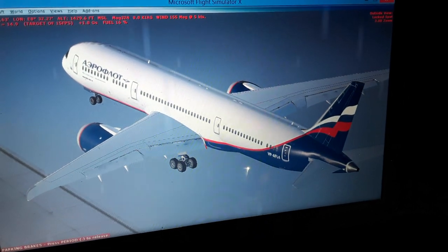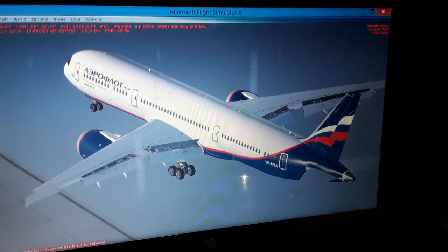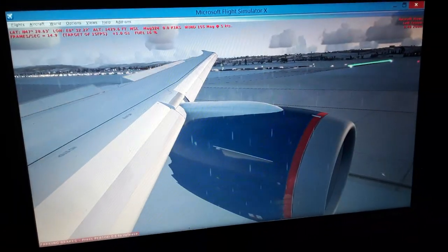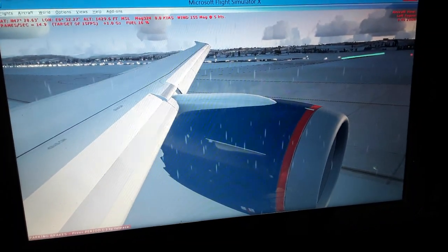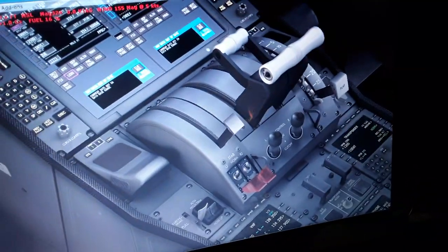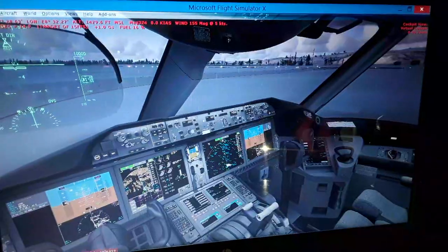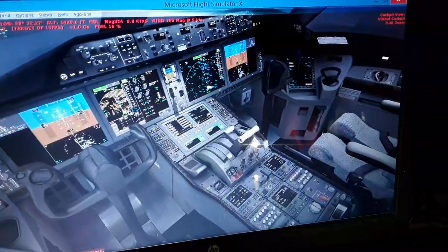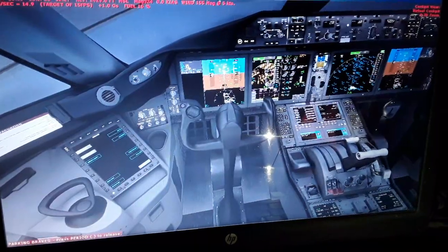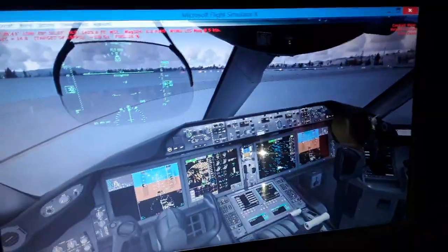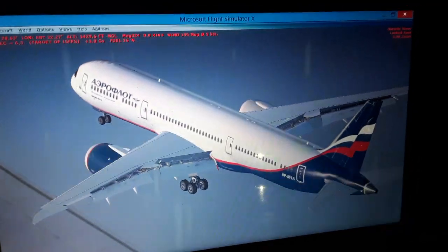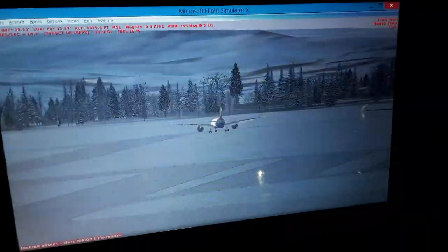Also the speed brakes here, we can extend at any moment. They're also used for turning the aircraft in flight. So this is this handle over here, what it's doing, extend and retract. So this is for landing. We extend fully to slow down the aircraft during a landing touchdown or a rejected takeoff. Perhaps in the air there is less deflection than on the ground.